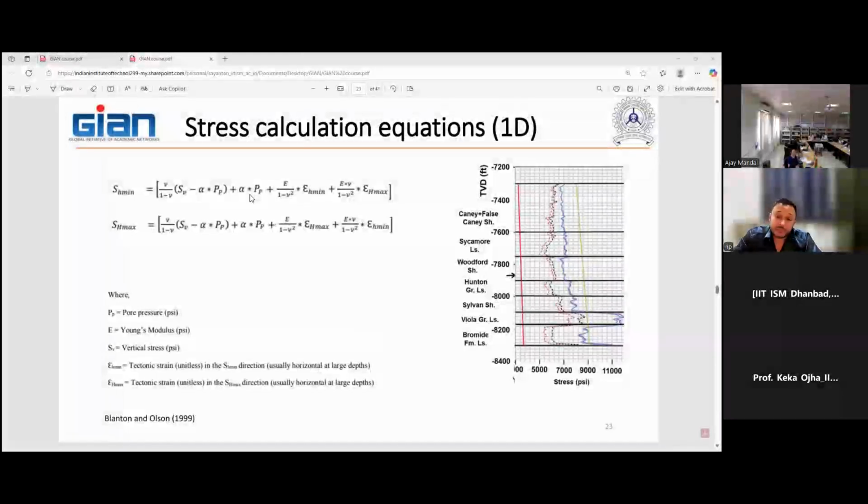So this part of the horizontal stress is coming from the vertical stress, the Young's modulus and pore pressure. Even if you had no tectonic stresses, you would still have these horizontal stresses. Why? Because once you put a vertical stress, your rock will try to expand sideways, because of the Poisson's effect. But if it cannot expand sideways because it's in the subsurface, then it will generate some stresses. So this part is that stress because of the weight of the rock.